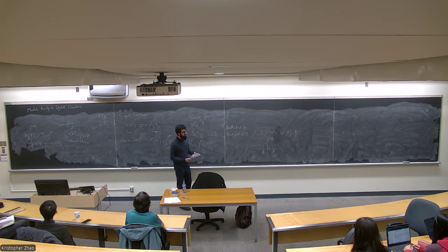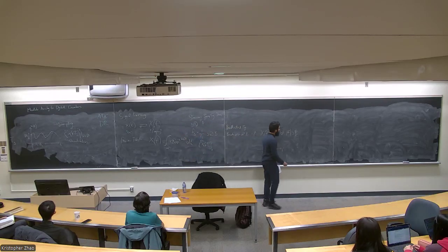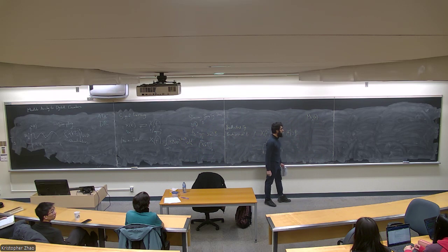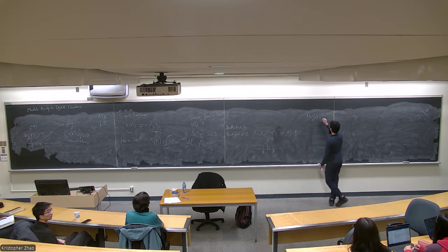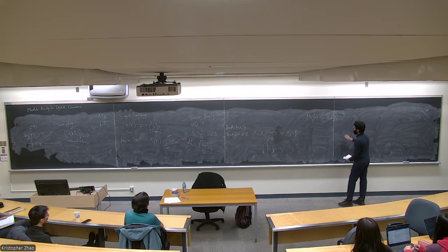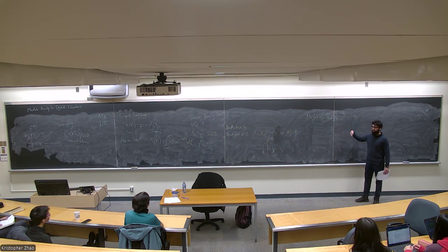Now I'll go towards the mathematical model behind modulo ADCs. Specifically, the first thing that we're going to do is define a modulo operation. I will denote that by M lambda of x, and that will be given by the following. This expression looks kind of unintuitive, however, it's just representing a shifted modulo operation.